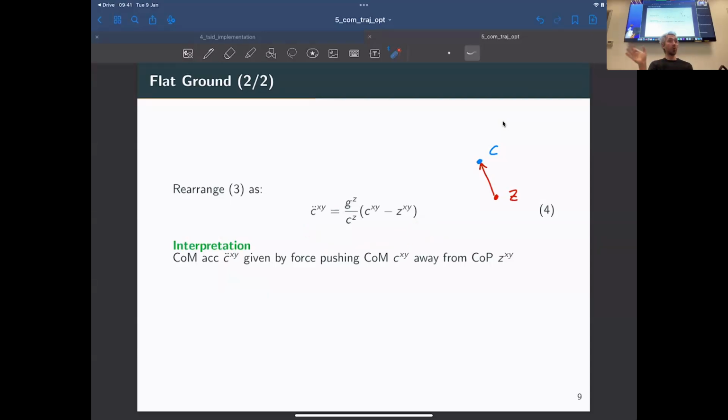Even quadrupedal locomotion can use this. This is not specific for bipeds. This is specific for locomotion on a flat ground. That's the real assumption that we are taking. But people actually use it also for climbing stairs, and with some tiny adjustments, it works as well.